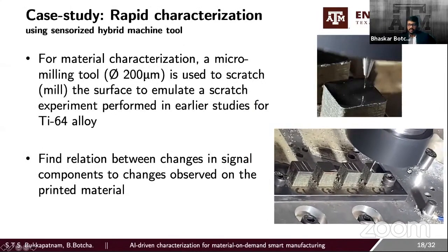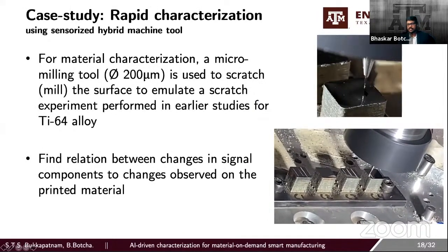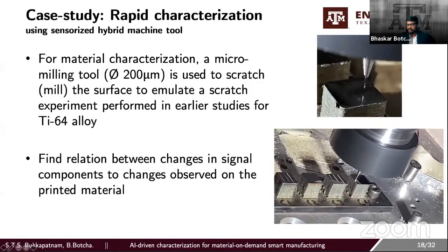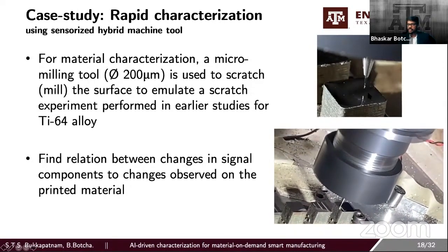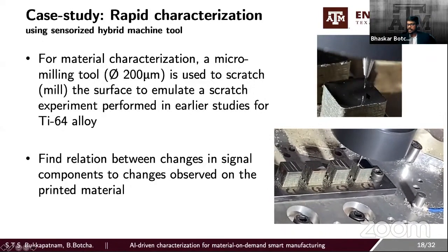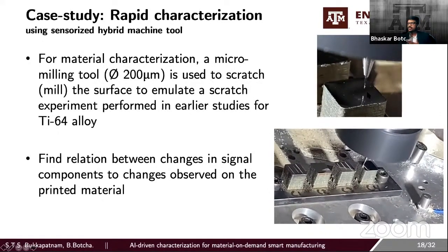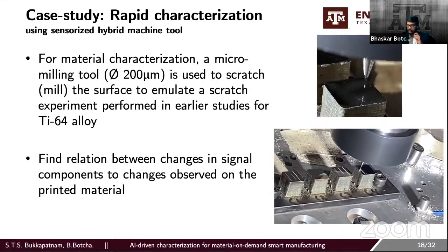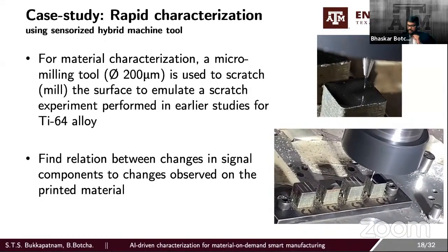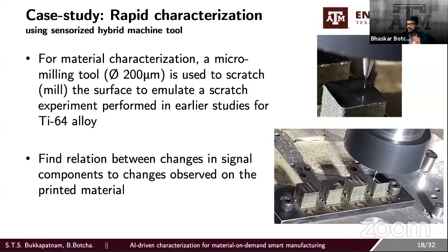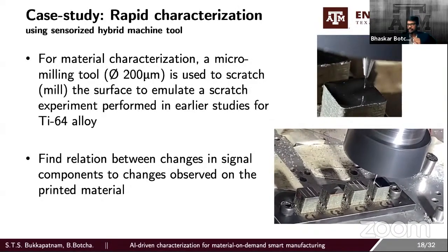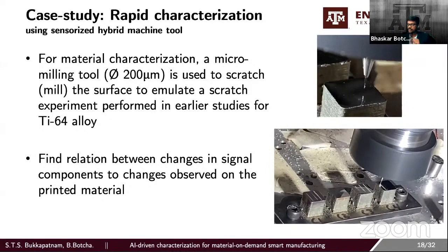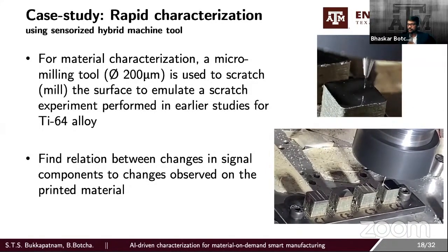So this is the hybrid machine tool, and the concept is simple. We brought this particular part, which has been fabricated in the machine itself, to a submicron finish. And what we do is, in a nanolithography experiment, we have a static tool which has scratched the surface, and we could find discernible features which can say if it is microstructure 1 or microstructure 2.